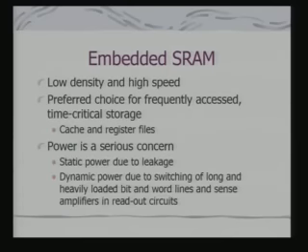Externally, when you are interfacing, your selection of memory block has to be dependent on these parameters, and that will also dictate the speed at which external transactions can take place. A typical feature of an embedded SRAM would obviously be low density, because I am using 6 transistors per bit, and high speed.